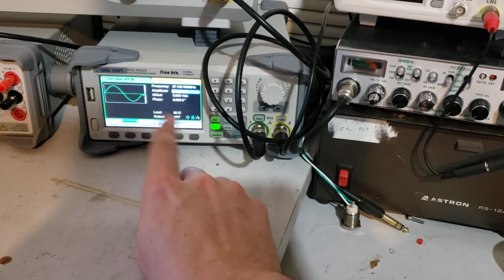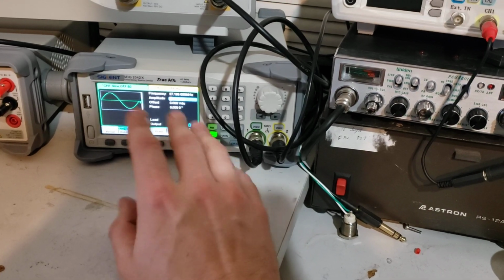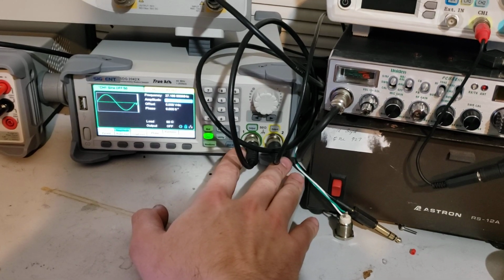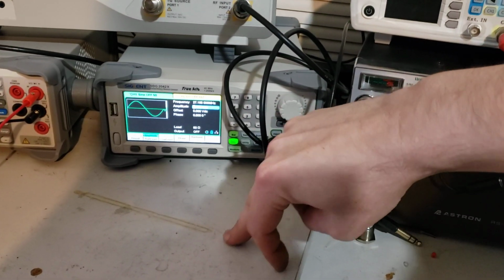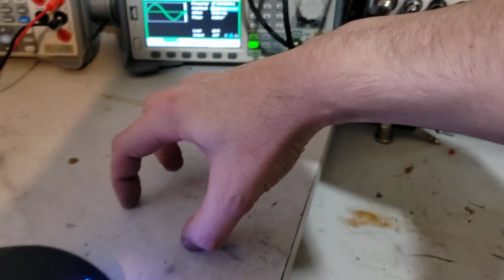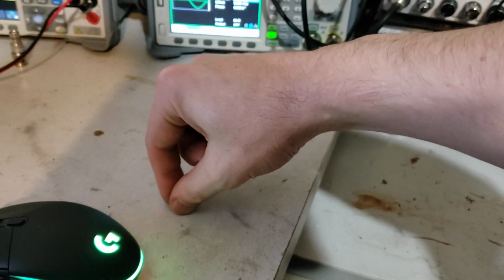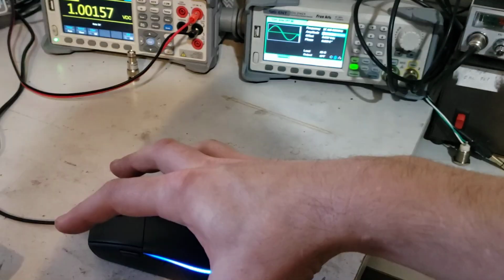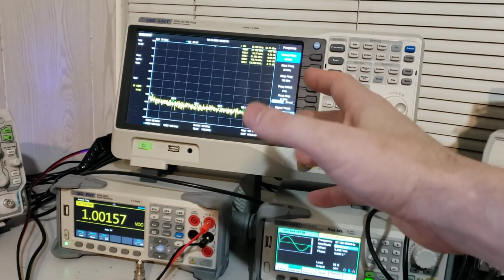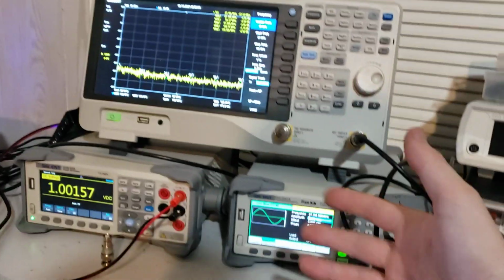I might use this for an AM waveform generation, but mostly what I want to do is use this for a two-tone IMD test. So the idea is that the signal will come out of here, and there'll be two amplifiers. That signal will go into two amplifiers, and then the amplified signal coming out will go into a combiner. That combiner will feed the two-tone signal into the amplifier, and the spectrum analyzer will be able to read the IMD, the intermodulation distortion characteristics of that signal.